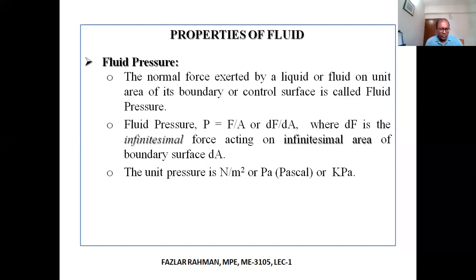For example, you are working at Eastern Refinery, and you have a pipeline system with a pump that should run for 20 years, but it breaks down after 10 years. Then what will be your investigation? You should look at whether there is any cavitation in the system. If you look at the pump impeller, or if you have a turbine, look at the turbine blade. Is there any pit or hole? That means there is cavitation. And what will be the effect of cavitation? Not only is the service life reduced, the performance or efficiency of your pump or turbine blade will be reduced. Okay.